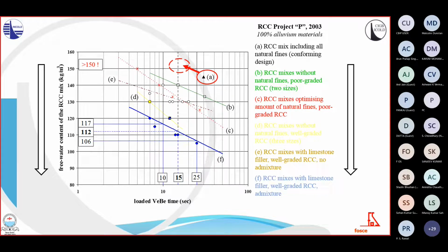Following a value engineering proposal, some additional cost was proposed to be spent in an aggregates processing plant that would crush and classify the coarse aggregate. The cost of such treatment was worth it, as the subsequent reduction in the water content was quite significant. The steps given during the laboratory design of the mix with increased quality of the aggregate are shown in the lines labeled with B, C, D, E, up to the final solution F that was adopted for the construction